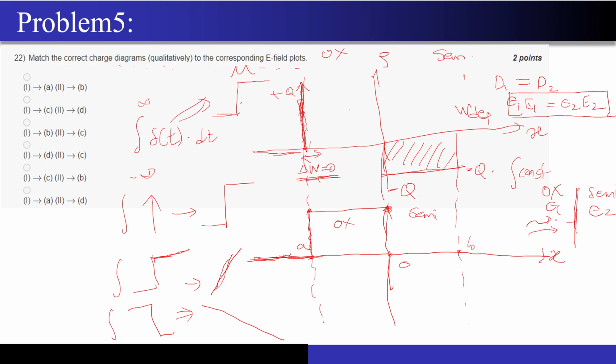To understand what actually happens, you have to apply Maxwell's equations. So just remember that the electric field is not continuous across this interface. The only thing that is continuous is your flux, and the flux is given by epsilon times E. Since the electric field is not continuous, what I have to show over here is that there will be a drop in the electric field.